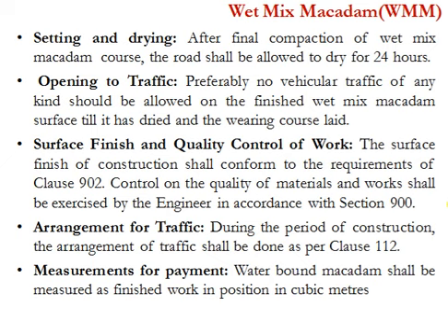Yes, the next process after compaction is setting and drying. After final compaction of the wet mix macadam course, the road shall be allowed to dry for 24 hours. So once the wet mix macadam is compacted, the road should be allowed drying and setting for a time duration of 24 hours.